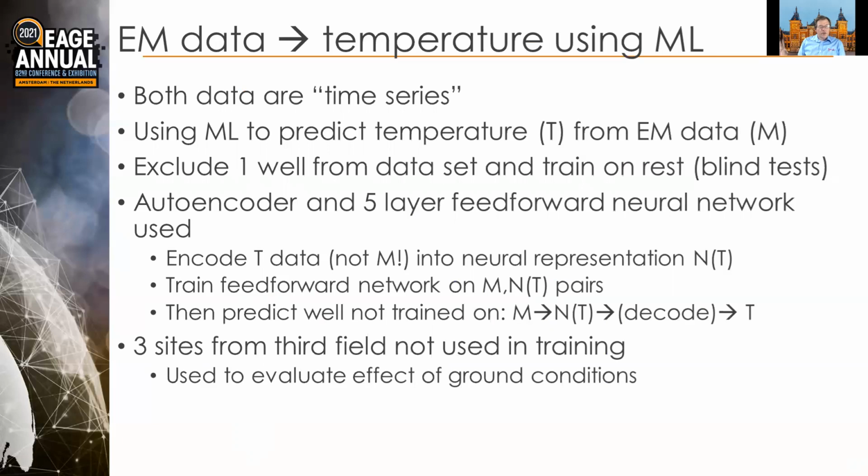First of all, we compress our temperature observation well data into an autoencoder network to simplify the task of the final network. It turns out with just 5 numbers, you can get a pretty good parameterization of the temperature profiles, because the temperature profiles are not random. They are shaped by steam injection. If there's no steam injection, it's just a standard gradient, slowly increasing temperature with depth.